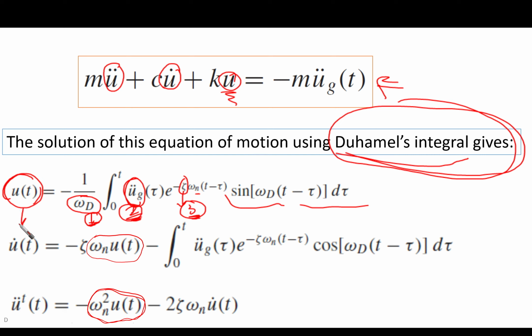And from here we can take the first derivative. This is the velocity, and this is the true velocity. Now we call this the true velocity coming from the equation of motion. When we try to derive this equation, we found that this very long equation here, seemingly this term is going to be the same as above. And we have here something very interesting. We found that the first term is going to equal the damping ratio times the natural circular frequency times U of t. Take care of this term. I'm going to indicate it later.